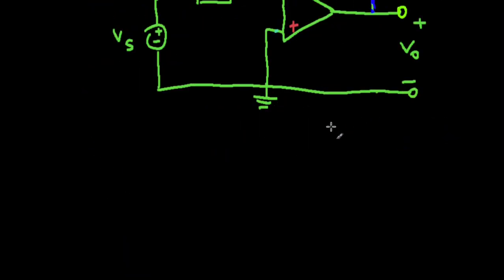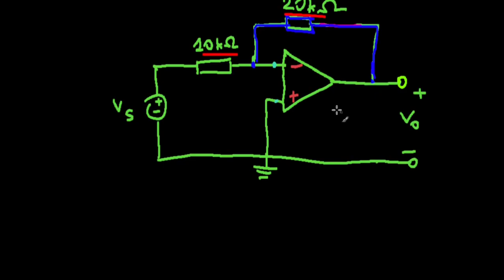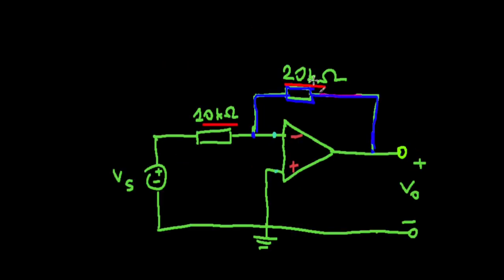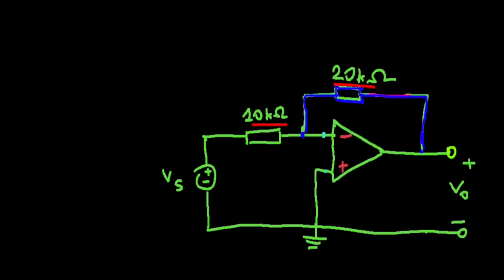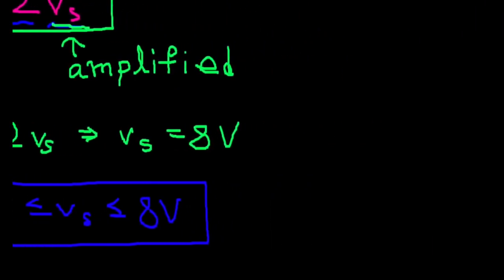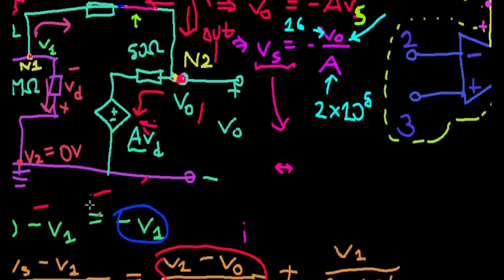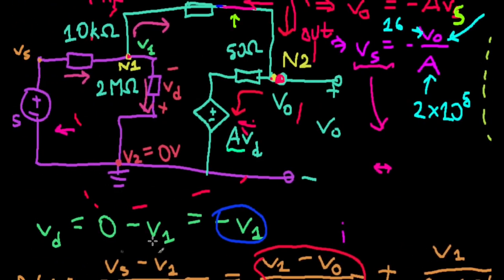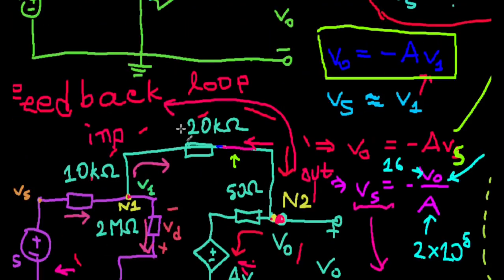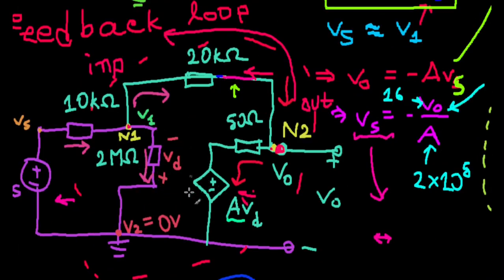The other thing is that when you're assuming that an op amp is ideal, the way you solve the problem is a bit different than what we did with the non-ideal one. Unlike what we did here, you actually don't need to break the op amp up into its equivalent circuit portions.